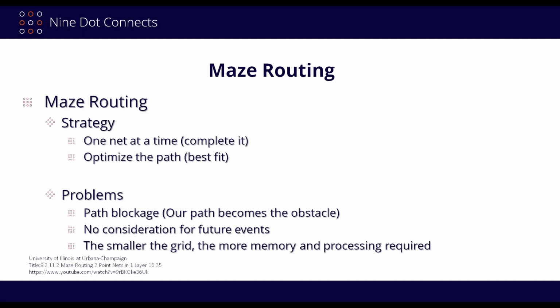It just says, okay, what's the next net? Where are they located? And let me see how I can get this net from point A to point B. And that's why a lot of times when you look at some of the routing results, you're like, this is crazy. Why did it do such weird jogs? It's because it didn't understand the proper order, because it's just going down a net list and saying, well, this is the next line, I'll take this one. Here's the one after that, I'll use that one. And that's all it's going to do unless you somehow give it some priorities.